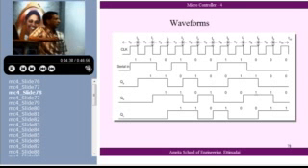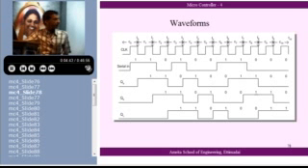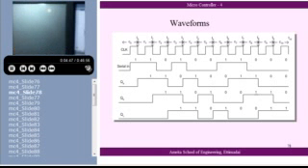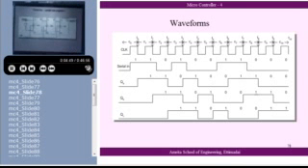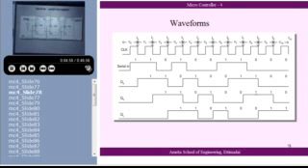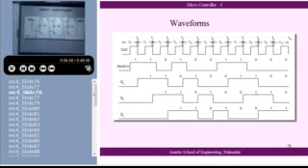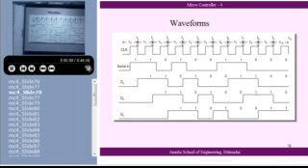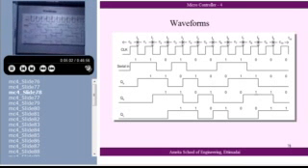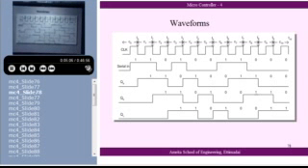Going back, if I take this flip-flop, when this input is 1, J is 1, K is 0, at the next clock pulse, this 1 will be transferred here, this 0 will be transferred here. That's all. Okay? At the next clock pulse. That's what I'm explaining here. Input is 1 at the clock pulse. QA will take state 1. QA bar will be 0.